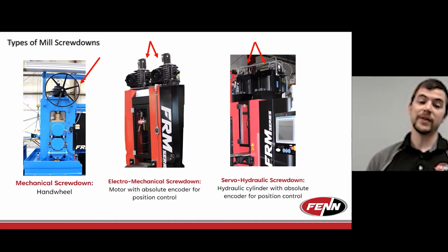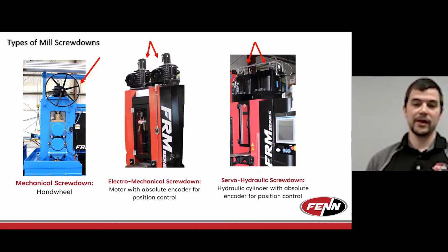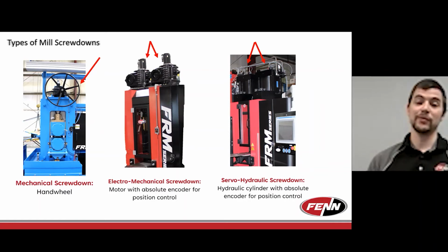These are mainly used for applications where adjustment is not that critical, where you're trying to keep the costs down or things like that. We have an encoder reading to give you the idea of where your position is at any time, and you physically turn it, moving the upper roll up and down accordingly to gauge for your thickness. So it's usually a lot less precise, and it's more of a set and forget type of adjustment, and it's used for basically 2 types of industries.